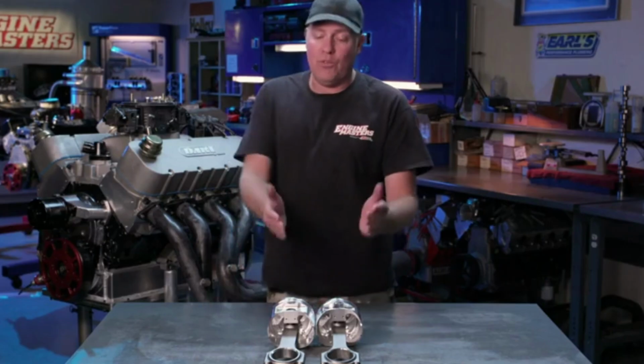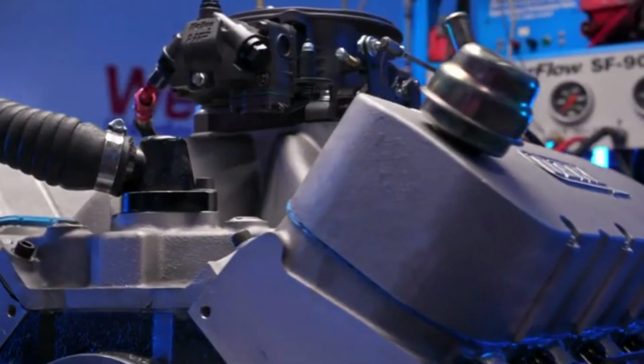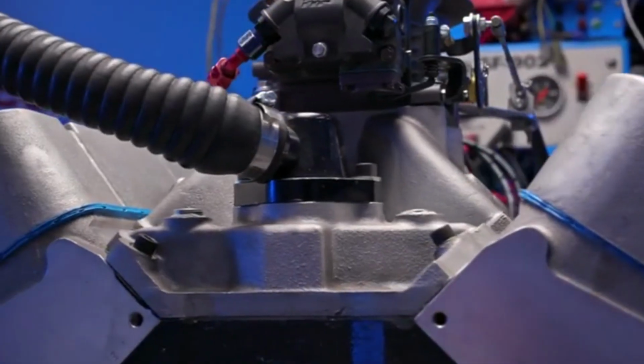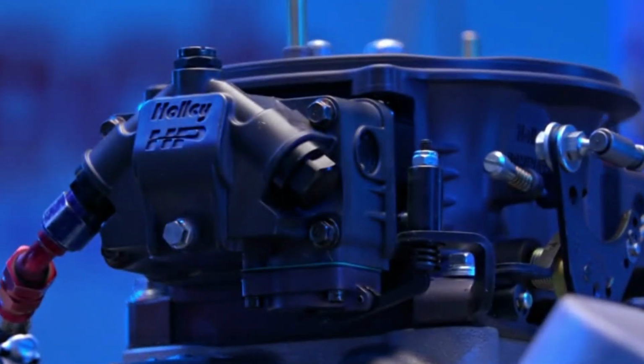So that's how I've specially built the low end here, and I really have to thank everybody at Race Winning Brands for working with me through all of this. Now let's talk about the basic specs. The cylinder heads are a Dart Pro 1 CNC aluminum deal, 365 inlet runner. And at the top end, I've got a Dart single plane intake manifold and a Holley 1050 Dominator carburetor.